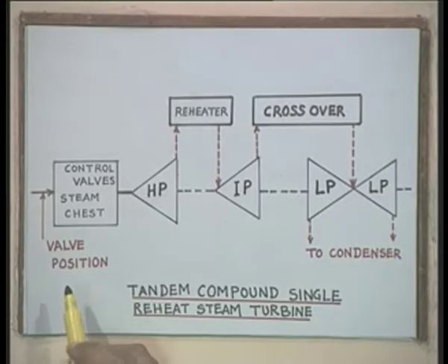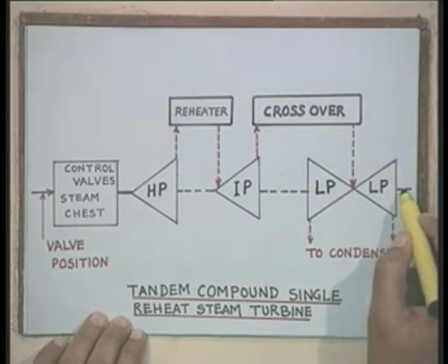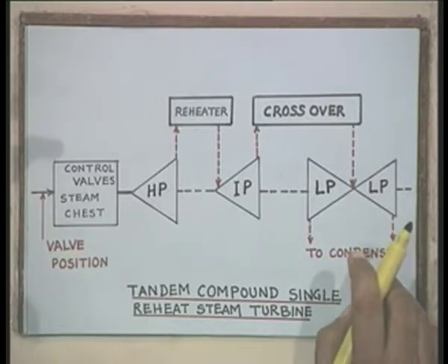If they are independent, then they become actually independent steam turbine sections. Okay. Now, our interest is to develop the transfer function model relating the power output from the turbine, and the turbine output is denoted as mechanical torque or mechanical power.